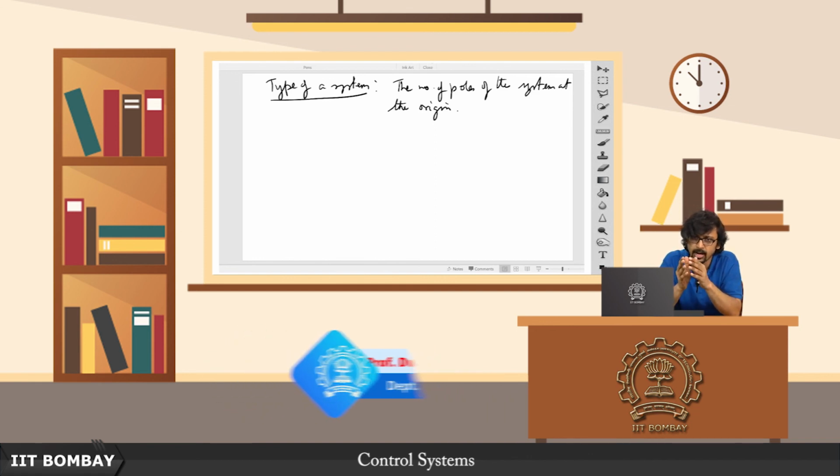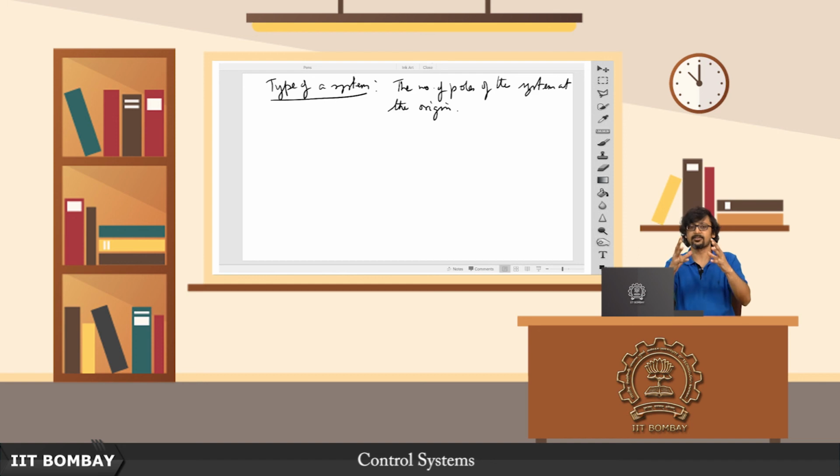The more the integrators you add, the more the number of inputs for which your system steady state error will go to 0. We will see that in the form of a table in the next lecture. We will start with that and then go on to explore a few more topics until we address this fundamental question of stability. The first thing we will see is Routh-Hurwitz criteria, which will aid us in evaluating the stability of a system. That is all for today.